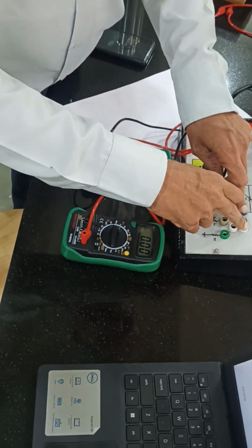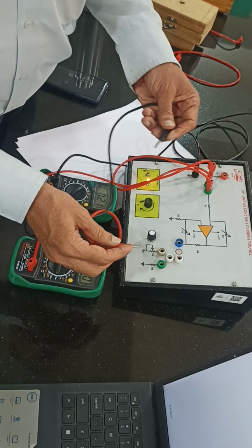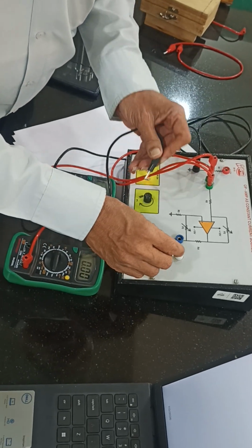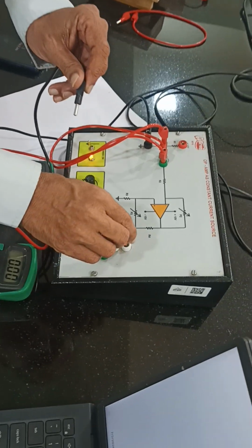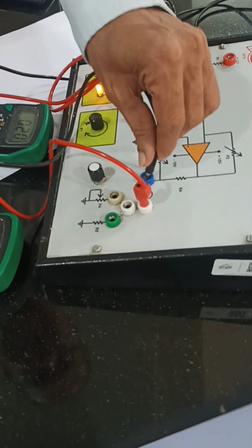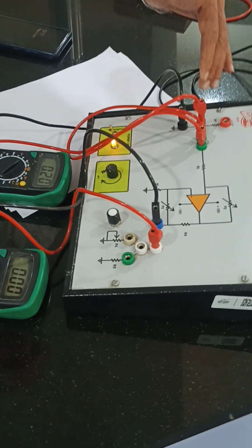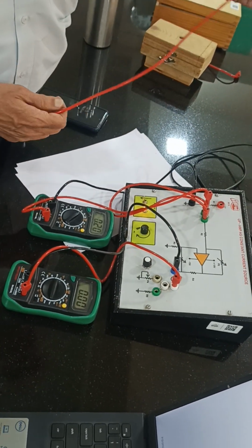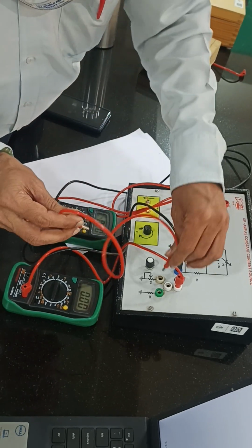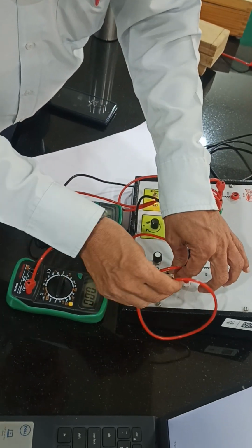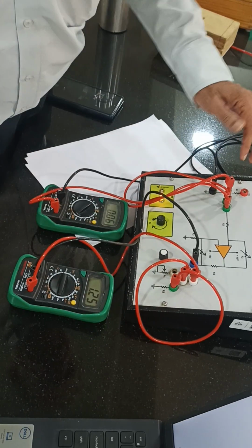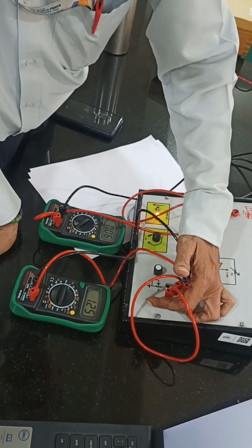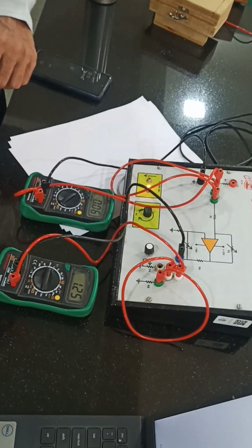Here between these two terminals we are going to measure the output current. So this is input voltage and this is output current. So the connections are to be made like this. Positive is here and negative is here. Now whatever current flows through the circuit, you have to give some path to that current. So you have to connect this terminal with this one, so that whatever current comes here will be given a path through this resistor and then it will come to ground.